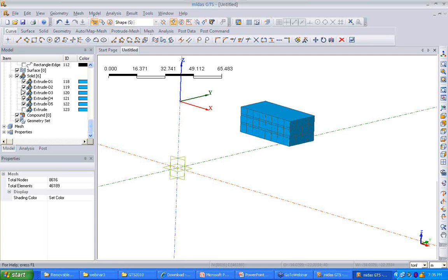As I informed in the starting, we'll be creating these retaining walls as per each excavation layer, by which I mean you don't put the whole retaining wall for the whole excavation ground in one shot, but you put the retaining wall for excavation one first, then put the structural elements, thus following the same construction sequence we discussed in the presentation. First excavate the portion and then activate the retaining wall and then activate the structural elements in there.